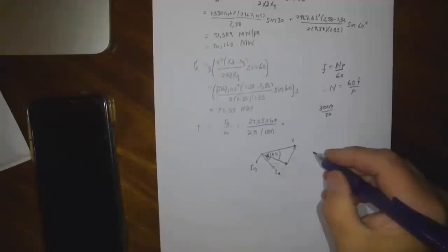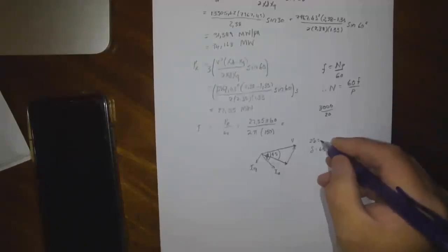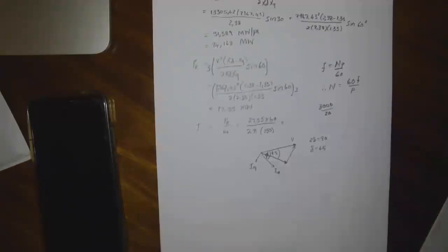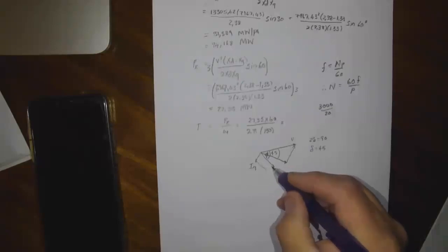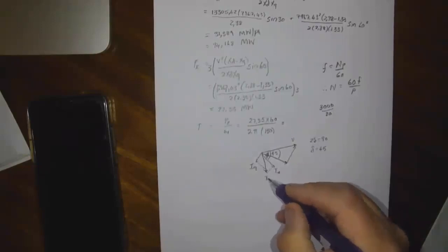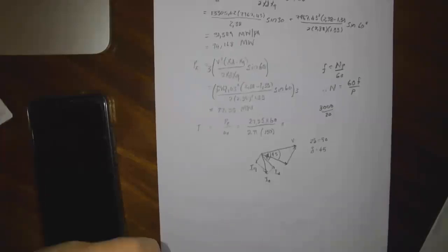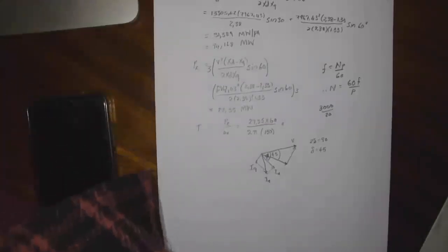So now, normally we say delta is equal to 45 degrees because 2 delta is going to be 90. So therefore, delta will be 45, and then we can calculate the current. Also, delta in this case is 45 degrees when my excitation is switched off. Yeah, because normally then it will run at maximum.